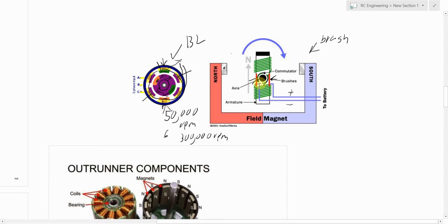And you see it actually has a gap right there and a gap right there. And you see that it's also wired to each of these armatures, to each of these coils. So what happens is as these brushes go around, it's only in contact with one commutator segment at once. Then another one will come in and attach. So sometime in the rotation, this will be a positive polarity, and sometimes when it's in contact with the other commutator segment, this is a negative polarity.